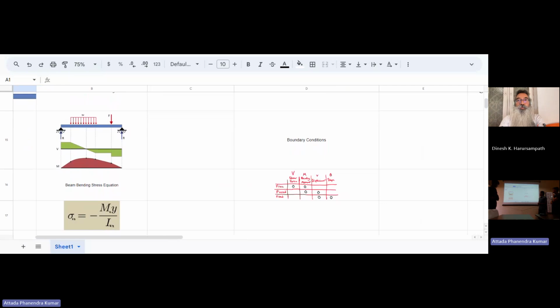And we mentioned that you can translate this bending moment into deformation, bending because it's a bending moment. But in order to do that, you have to include boundary conditions based on whatever support or fixture we're using. So in this case, we're using simply supported instead of pin. I have this small chart here that describes which boundary conditions are applicable based on the support. If it's a free end, you have zero shear force and zero bending moment at that location. If it was pin, you'd have zero bending moment, as you mentioned with this diagram, and zero displacement. If it's fixed, you're going to have zero displacement and zero slope, which is the derivative of the displacement.